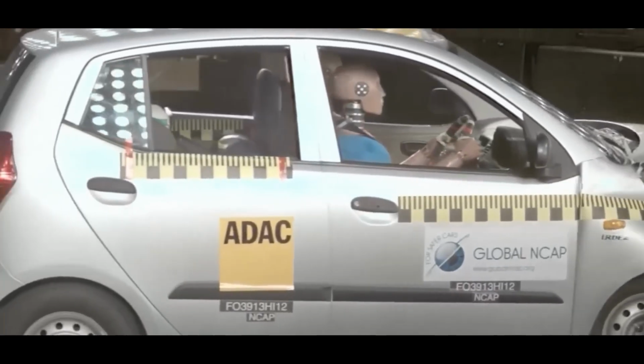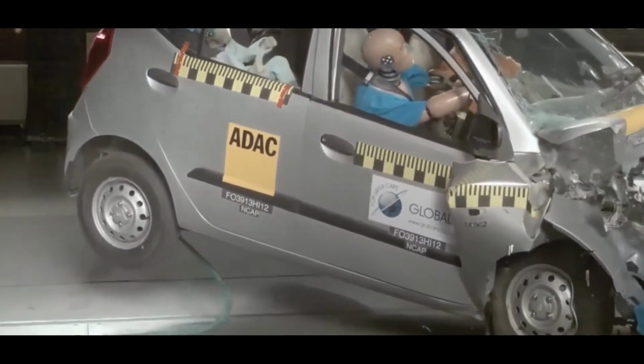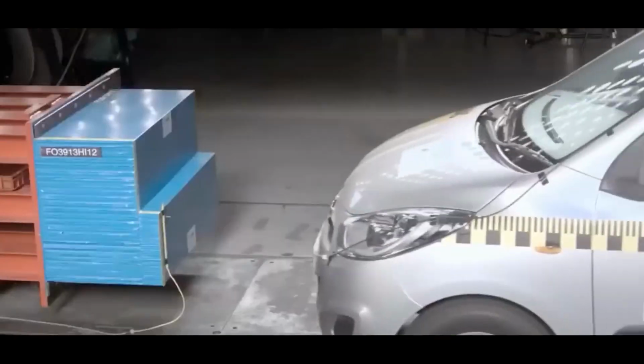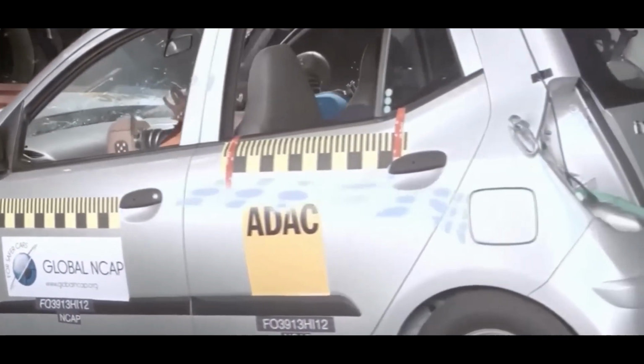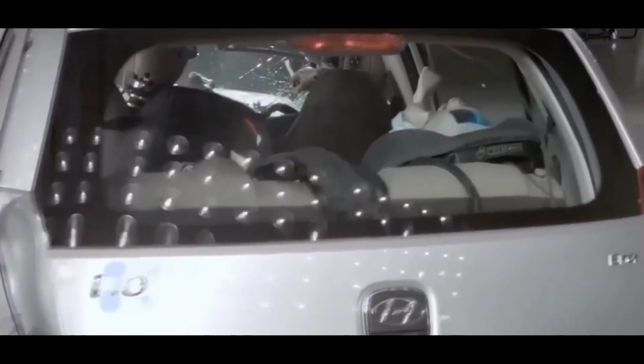Iteration 2. To improve stability and repeatability, the design underwent several major changes. The outer rods were connected using reinforced bumper structure, memory foam was added to improve energy absorption, and the phone mounting system was redesigned using elastic restraints and more secure 3D printed tray. These modifications significantly improved alignment, structural rigidity, dampening behavior, and repeatability between tests.